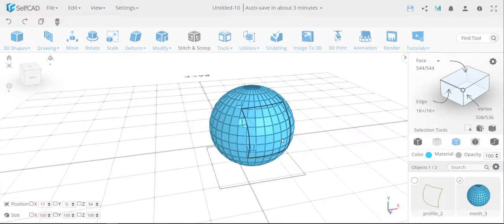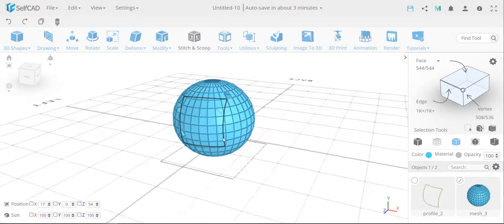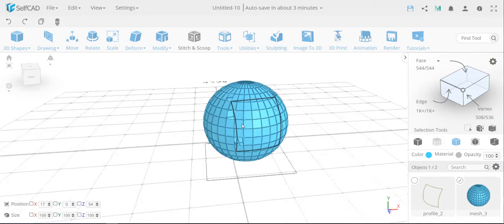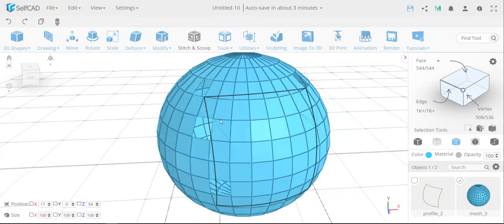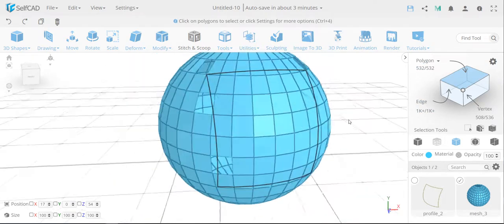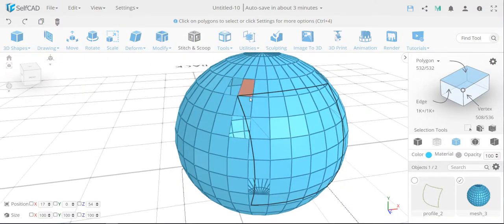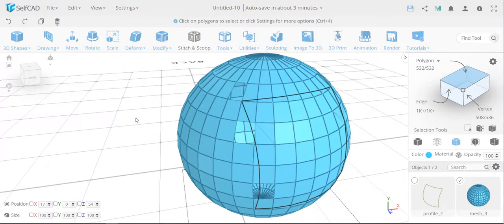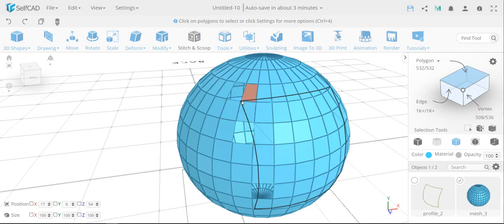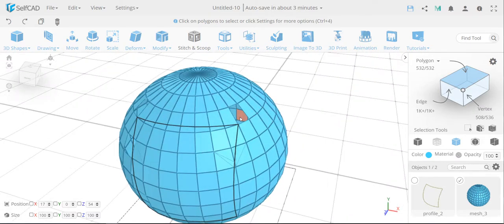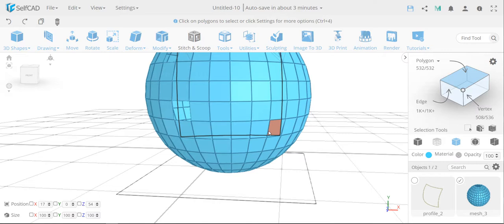Okay, so now you can see that in these particular cases, where you have very close faces and things, it may sometimes create holes. So the cut is actually done. Let's see if it is actually done. Yes, you can see over here, it did cut them. You can even select, if you go polygon selection, yeah, this wouldn't help, and I'll show you in a second. But you can see it created holes, and this gets created when they intersect, snapping, like this vertex snapped with this one and this with this one. So in this case, it's not perfect.